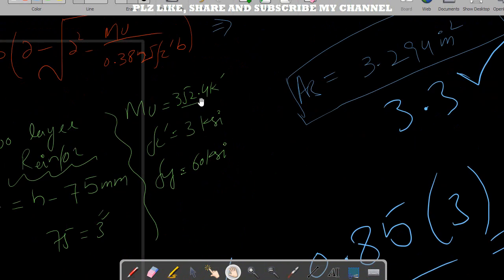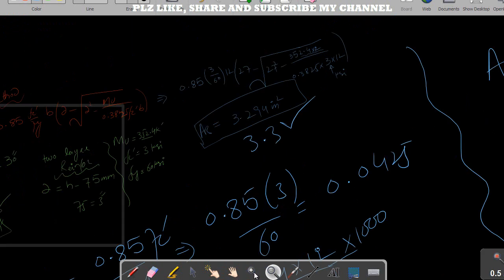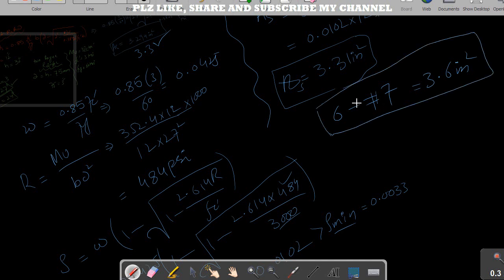For this area of steel, which is 3.331, we can cover this area of steel by using 6 number 7 bar. By using 6 number 7 bar, it gives us 3.6 square inches, right? So this is my final selection of bar. You people can use a different selection.